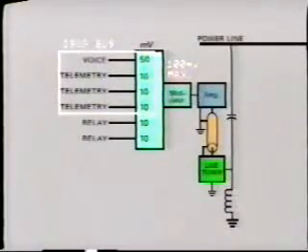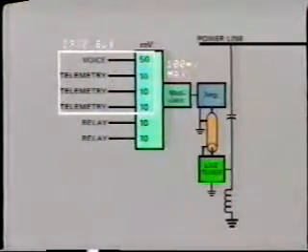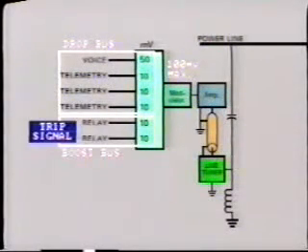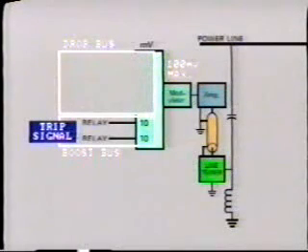The voice and telemetry inputs are connected to the drop bus, while the relay signals are connected to the boost bus. Now, when a protective relay sends a trip signal through the tone equipment, this contact initiation also disconnects the drop bus from the modulator.